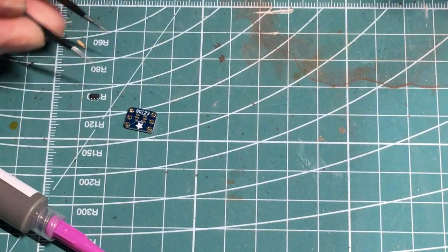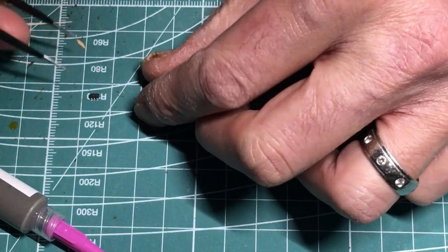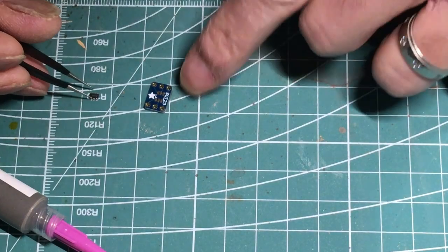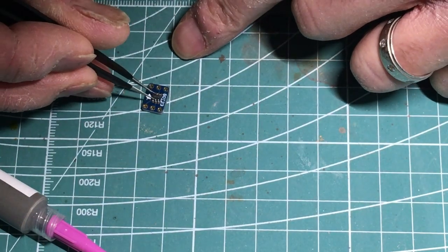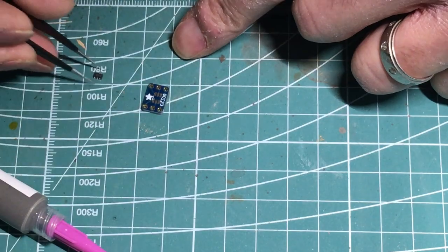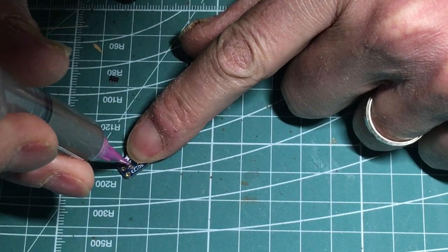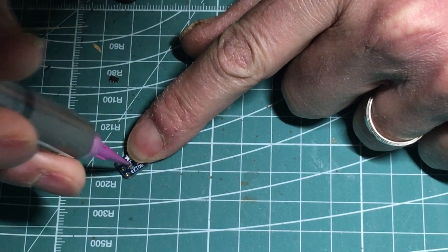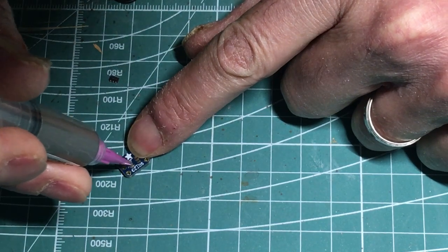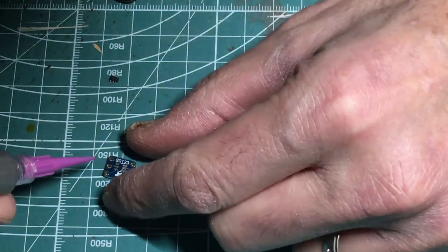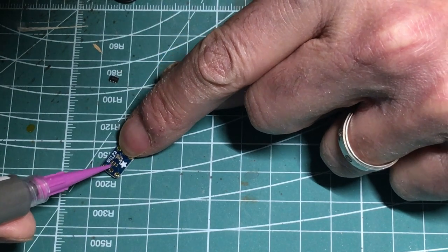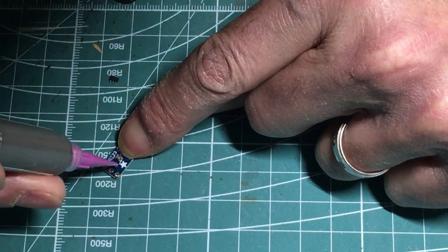Before we can build the circuit, we're going to have to take that tiny SOT23 chip and solder it to a breakout board so that we can use it on a solderless breadboard. Here I'm test fitting the chip on a breakout board that I bought from Adafruit. I've got a bunch of these for different types of chips. I found the best way to solder these in place is to use a little bit of solder paste. It doesn't take much, just the tiniest amount on the contacts.